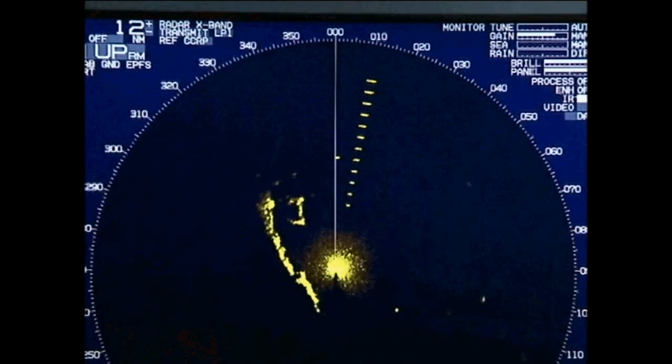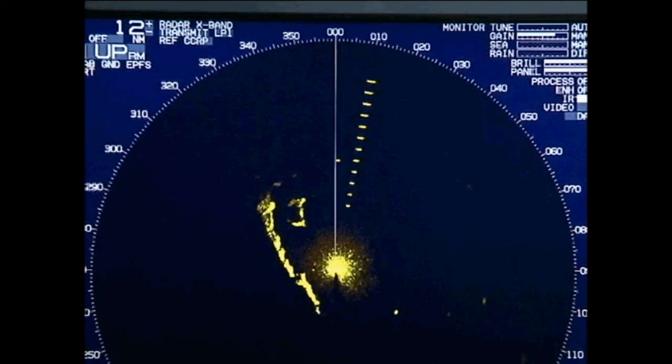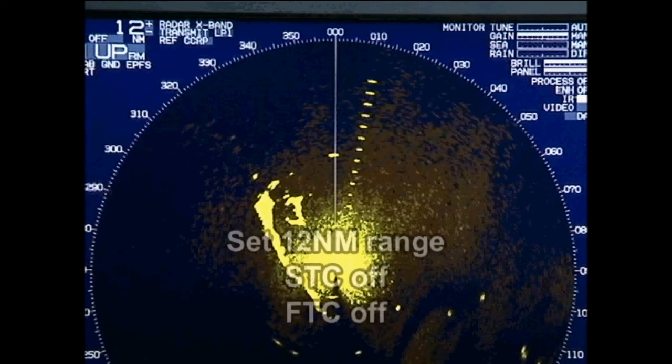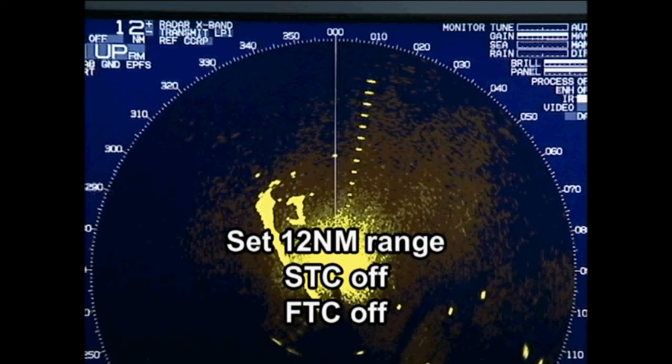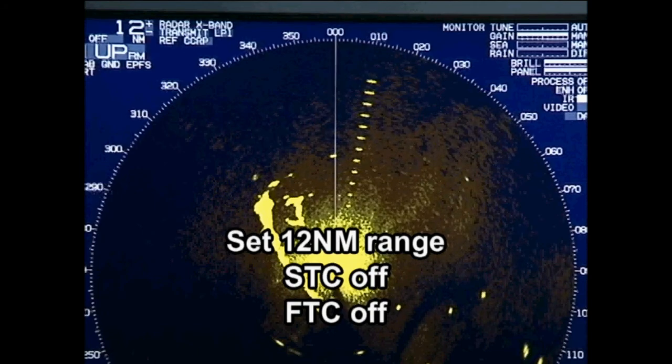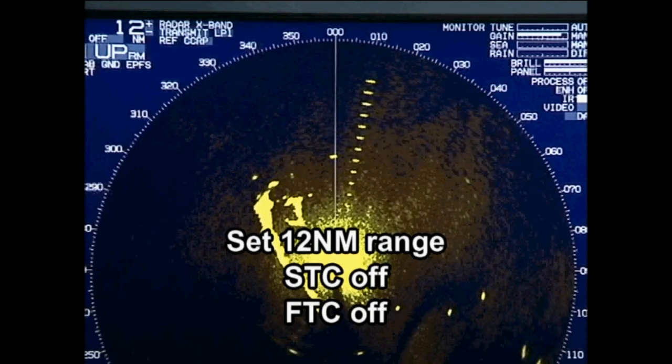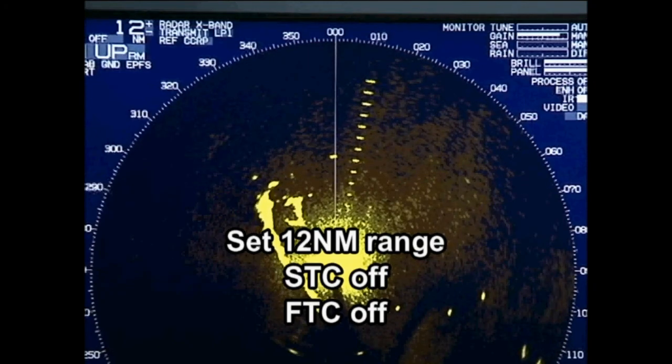When own ship has become a search vessel, carry out a search and rescue operation with the radar range set to 12 miles or greater. This is necessary because the SART signal appears as a 12-dot line extending out to the 8 nautical mile range, and the radar visibility range is about 10 nautical miles. To facilitate reception of a SART signal, the operator on the search ship should set the sensitivity time control, STC, and fast time constant, FTC, to 0. Once a SART signal has been found, let the rescue ship proceed toward the dot of the line closest to own ship.